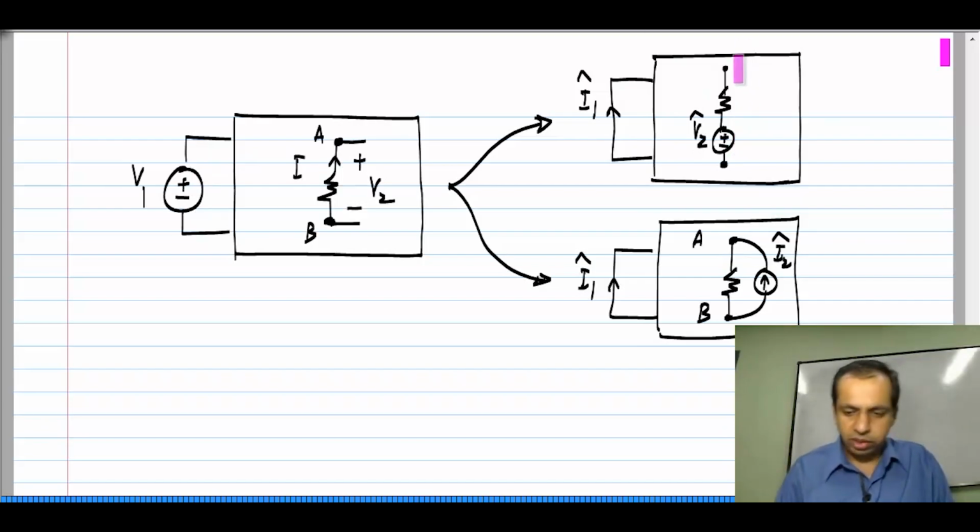Okay. Because in the first case, essentially what I am doing is I am defining, let us say this is port 1 and this link here is port 2. Then you can think of the original case as the case with port 2 being short circuited. Okay. And this current that I have marked is really the current in port 2, right. I have marked it on top of the resistor, but now the resistor is part of the 2 port. It is really the port current.